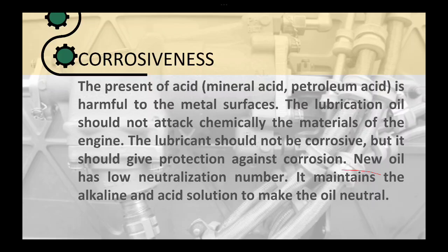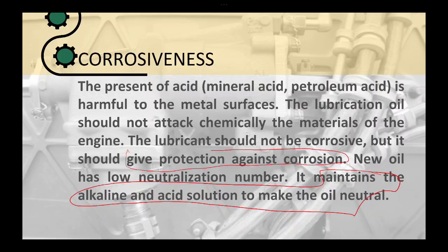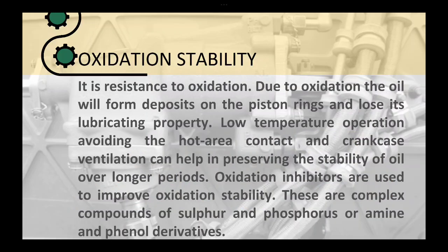So it maintains the alkaline or acid-like solution to make the oil neutral. Okay, gives protection against corrosion, and the lubricant should not be corrosive. That's corrosiveness. Next, we do have the oxidation stability. Oxidation stability is just the resistance to oxidation. Okay, the oxidation stability, resistance to oxidation.